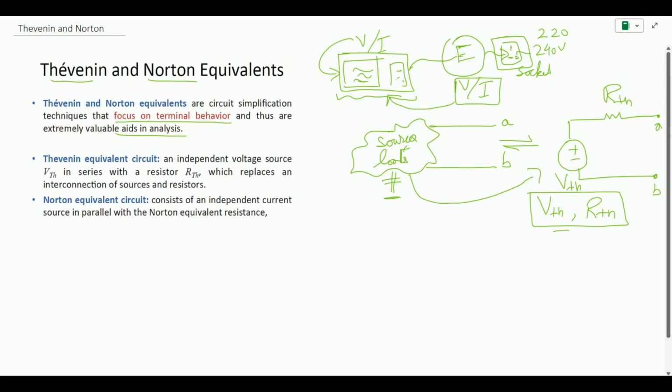And we believe that all these values will be equally contributed to by whatever number of elements were inside the original circuit. Similarly, the Norton equivalent also gives us a sense of the same currents and resistors for any multitude of sources and loads. In order to represent the Norton, we again have arbitrary sets of sources plus electric elements connected to any two electrical wires. We call these terminals.